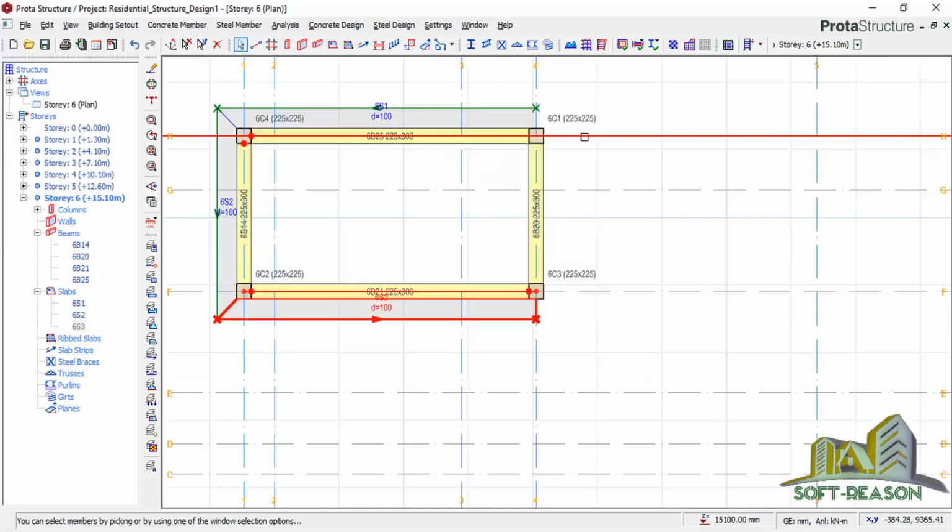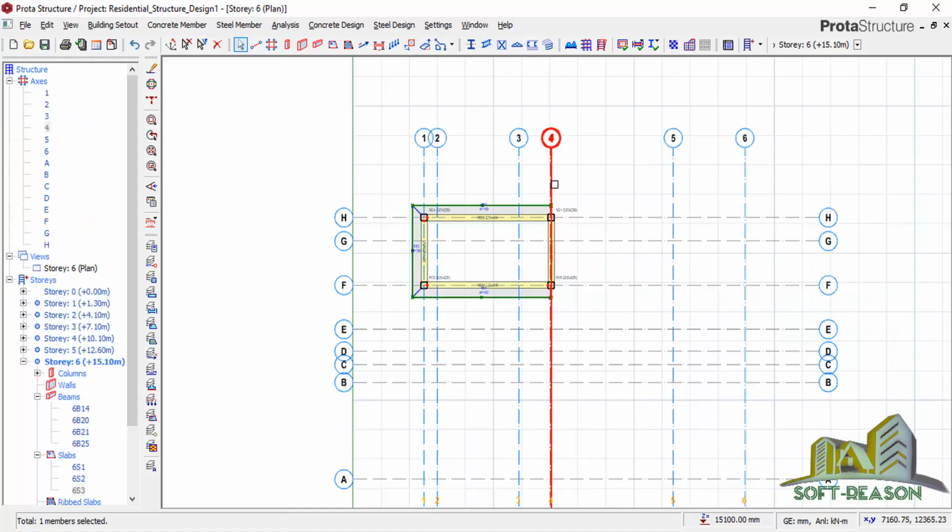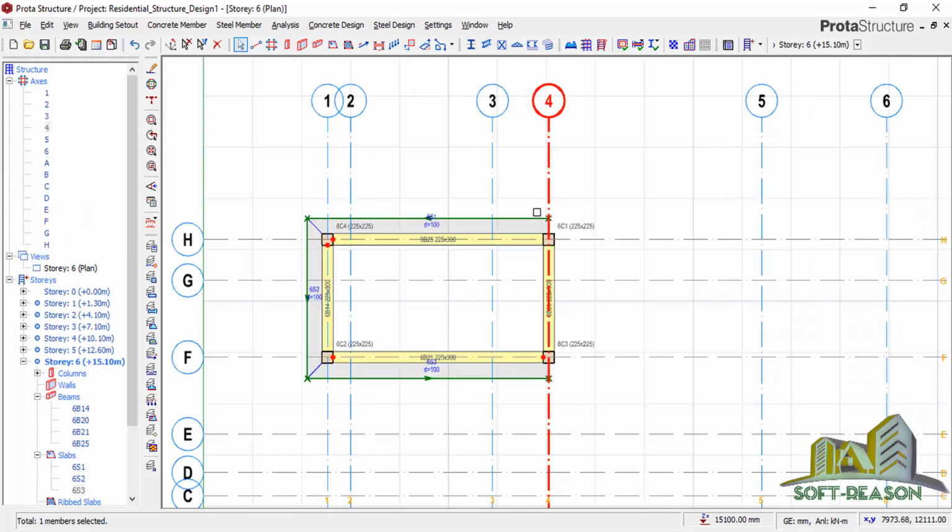Alright, so the next thing I will do is offset this line to this point out of this line, offset 450. So I'll right click on offset, move it like this, hold my shift key and then press 2 and then I'll type 450.